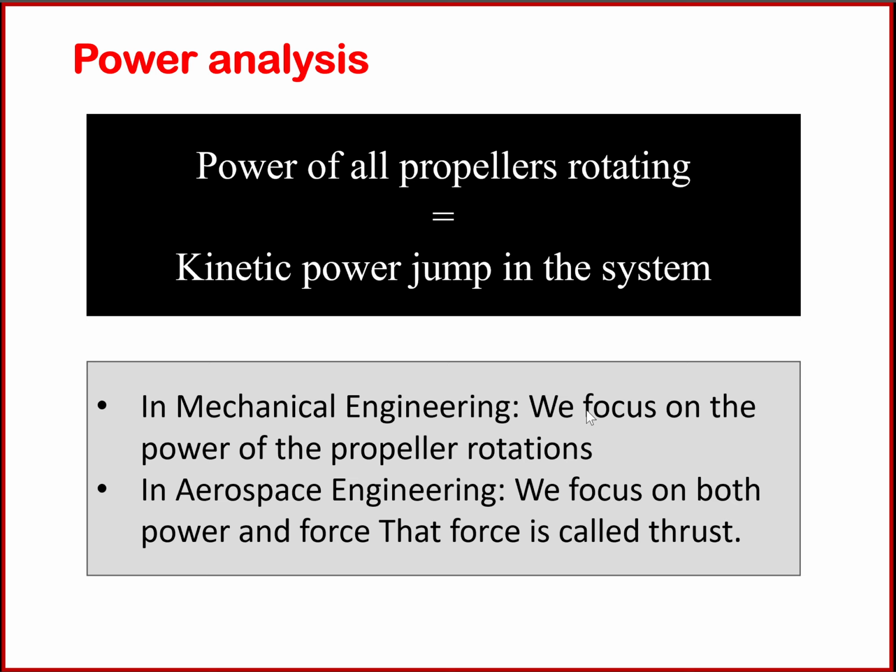Okay. But how can we analyze the power or energy that is added to the system or extracted from the system? The idea is the power of the propeller rotating is equal to the kinetic power jump in the system or kinetic power reduction, essentially kinetic power change in the system before and after a propeller.